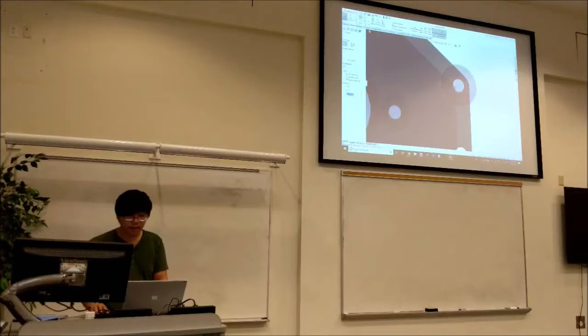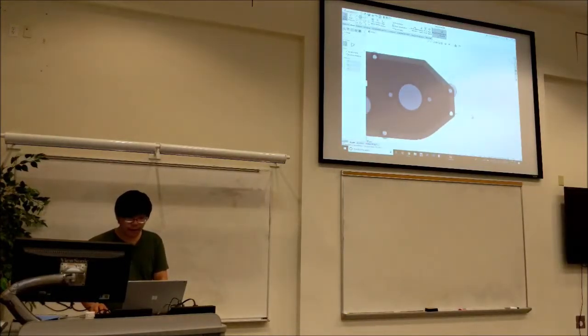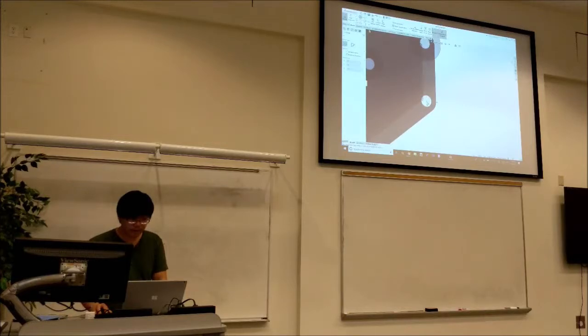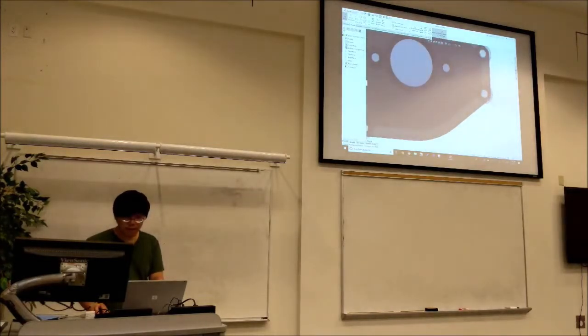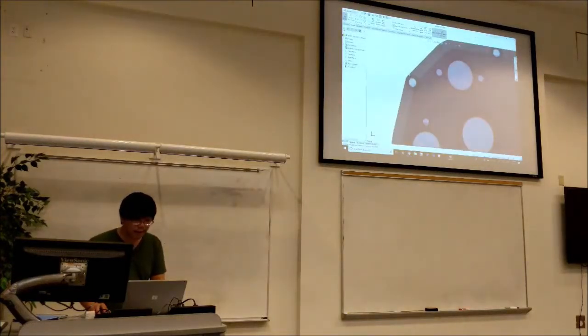So once you make sure your gearbox does work, then you can come back in and do this for your final part. So now we have all the holes, right? We want material around all of these, so we're just going to make them all equal. And you can make this tangent to this, because we did model the standoff earlier, right? Or co-radial. So that defines this material.